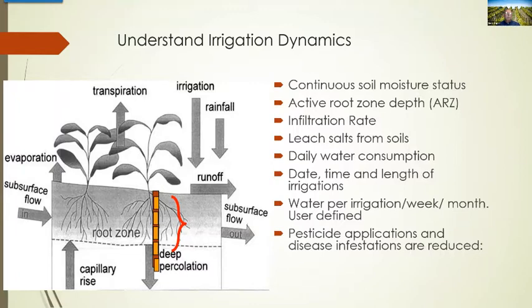So what happens when you run this system over these long periods, if your soil doesn't have a high infiltration rate, if it's not a sandier soil, but it's a heavier soil like a clay soil, you'll start to saturate that soil. That plant will stop respirating. And when it does, it drives the disease pressure.